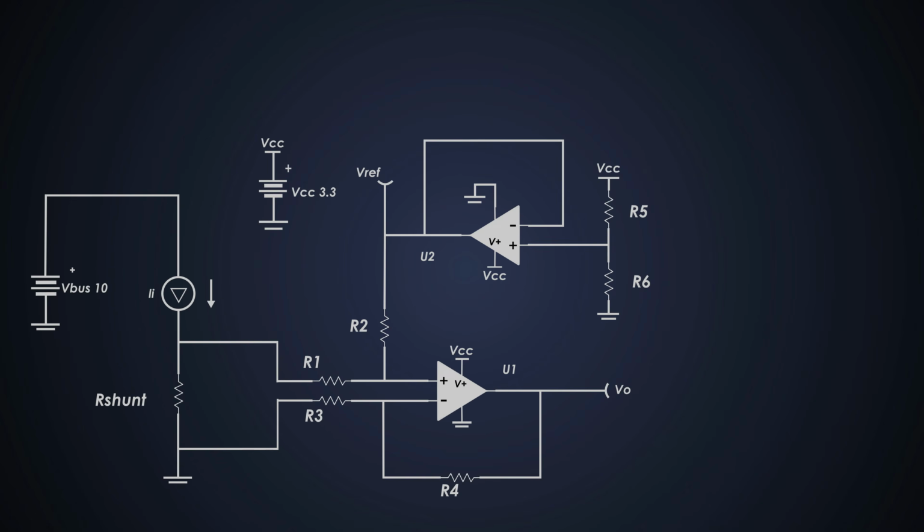To get the design of the right circuit, we need to keep some things in check. First is to maintain the shunt resistor value as per current. Then ensure peripheral resistors R3 should be equal to R1 and R4 should be equal to R2 to minimize the errors. And we should use precision resistors for R1, R2, R3 and R4 to get more accuracy.